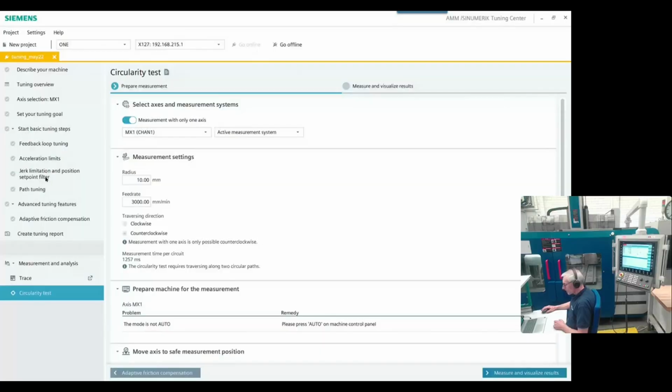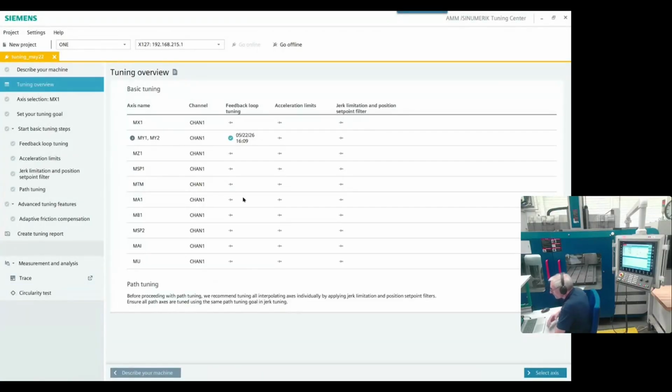So interesting. When I think between acceleration and jerk, I'm thinking of a trapezoidal velocity profile versus an S-shape velocity profile. I wonder what your thoughts are on that. Is there still any use case for trapezoidal velocity in a machine tool, or are we primarily introducing some kind of a jerk limitation to get a smooth S shape?